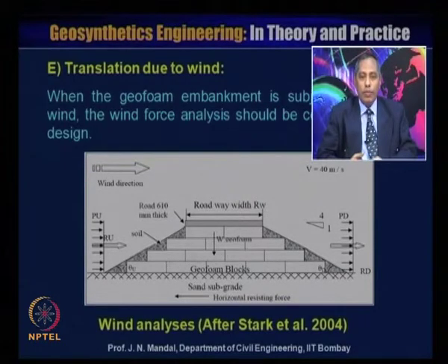This is very important, because when you construct the embankment on the subgrade soil using geofoam material, being lightweight there is a possibility of the geofoam flying off in that locality. Therefore, wind analysis is required. So, we will consider what will be the wind velocity in that locality and how you can design for the wind velocity.